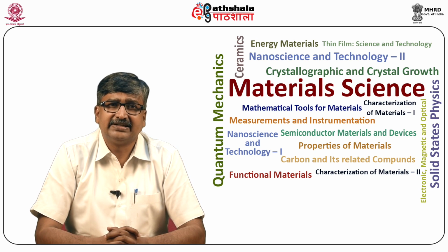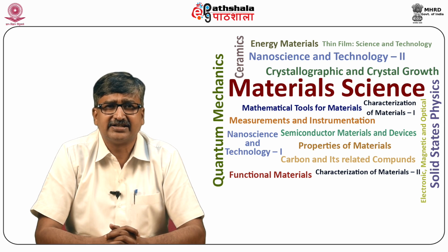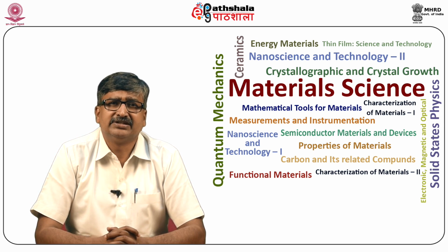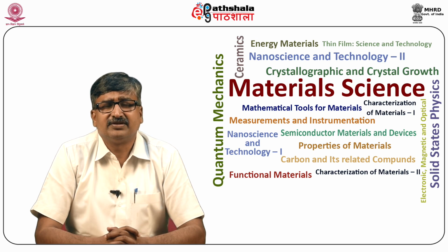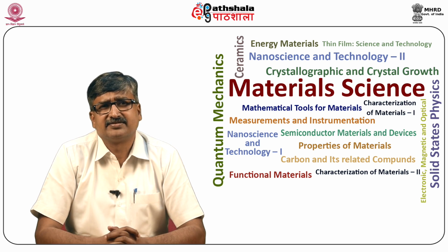Together with their strong interaction with light and relatively high charge carrier mobility, this has opened up the possibility of using few layer TMDs in a range of applications including ultrathin field effect transistors, photodetectors, light emitting diodes and solar cells.